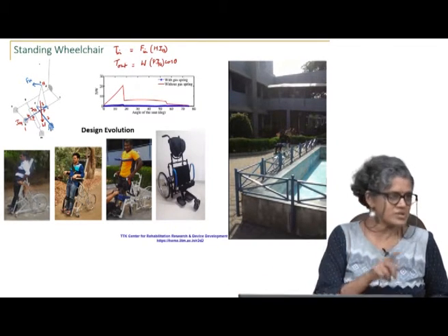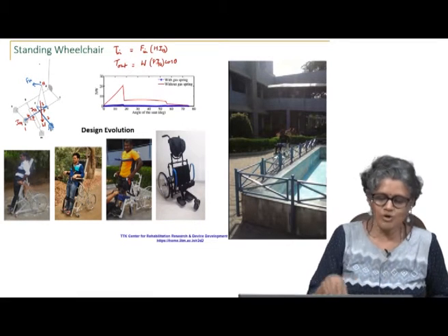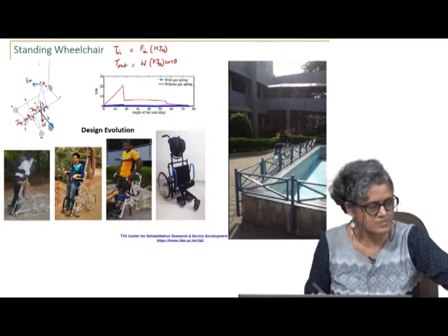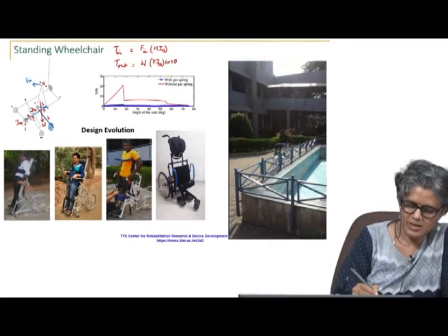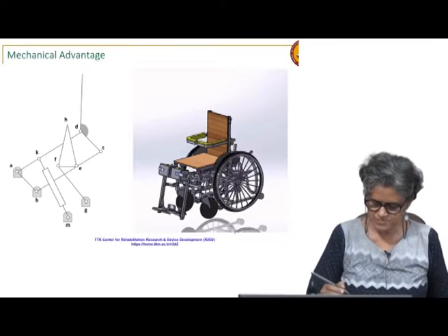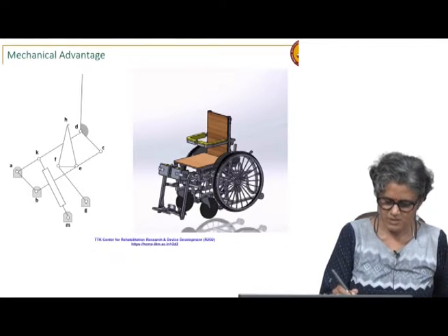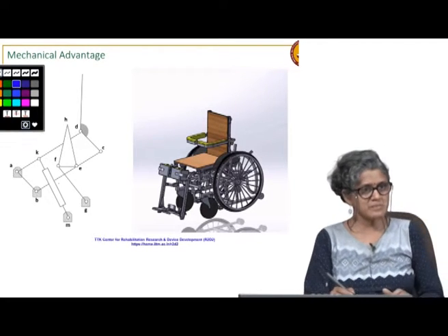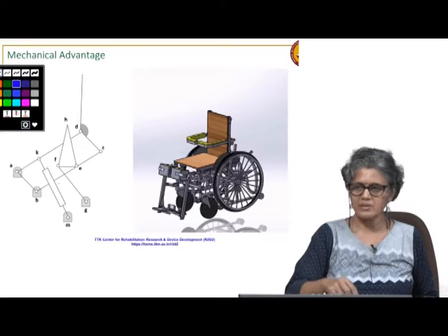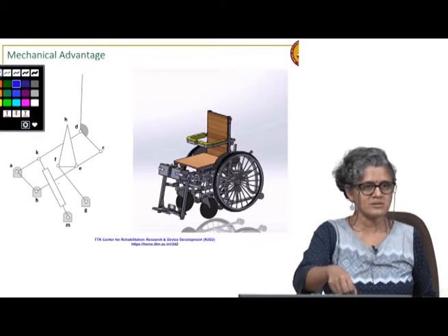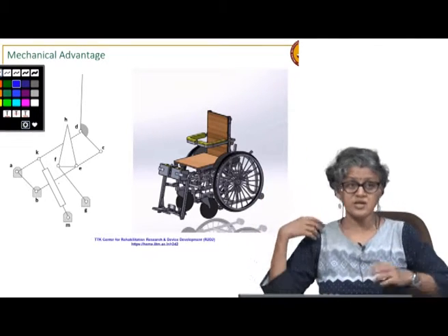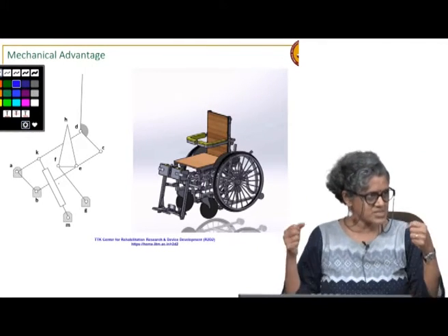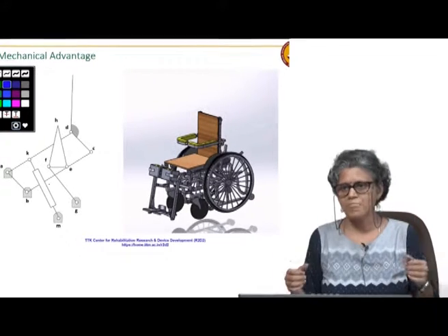It is only possible because of an additional link here. Here I would have to apply a pretty high force. If you look at the dimensions, I can't make H too high, because ergonomically I won't be able to push. I will be able to apply the maximum force at some optimum height.